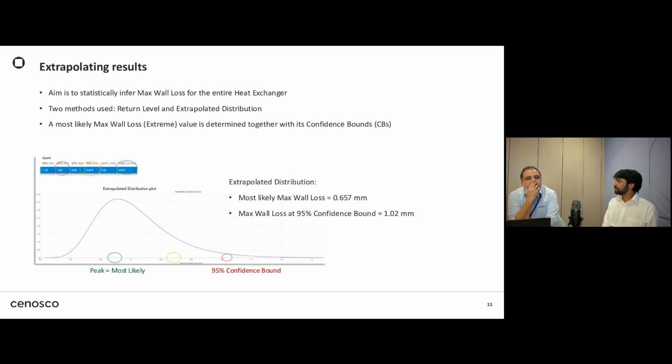It's just a quick one. Like I mentioned, we do have some other methods and methodology that we use to extrapolate the results. Also in IMS, we do have some other distributions that we analyze the corrosion rate with, right? And then we have the same confidence, like some of these Weibull distributions. Yes, we look at the corrosion rate, but in this case, that's the maximum wall loss, right? So on that wall loss, we calculate the remnant life.